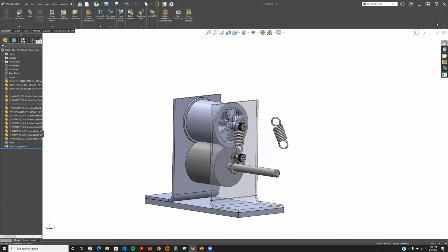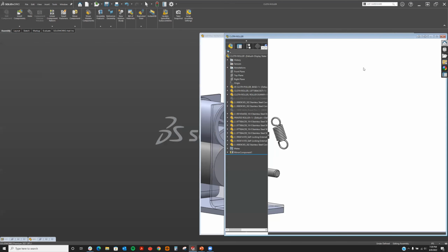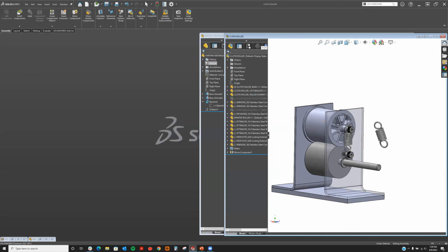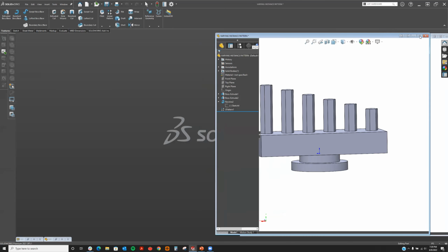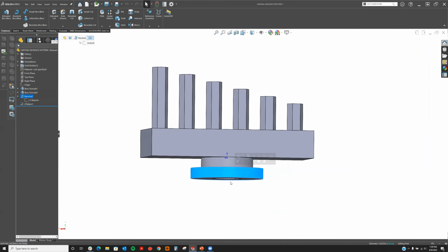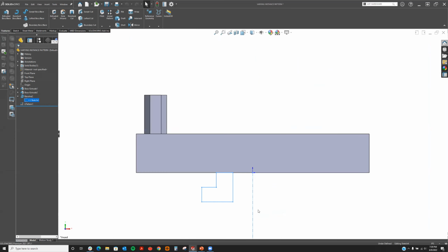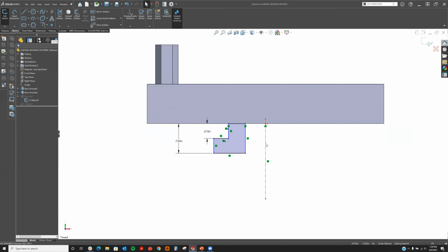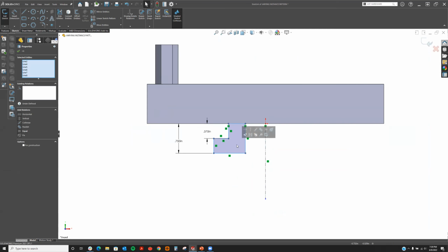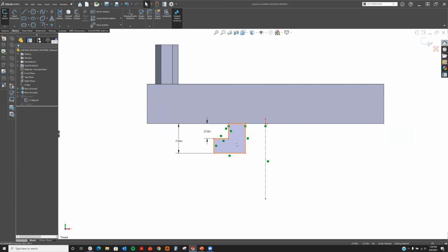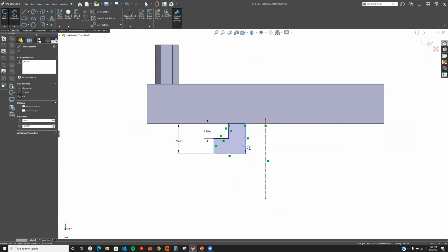And I'm going to try to show it to you in context so that it makes a little bit more sense here. So I've got a revolve feature on this little sample part here. I'm going to go into the sketch for that feature. Okay, so I've got my center line set up, right? And this is the revolved extrusion in this case. So I'm going to grab my dimension here, come off the edge. So that's the center line.